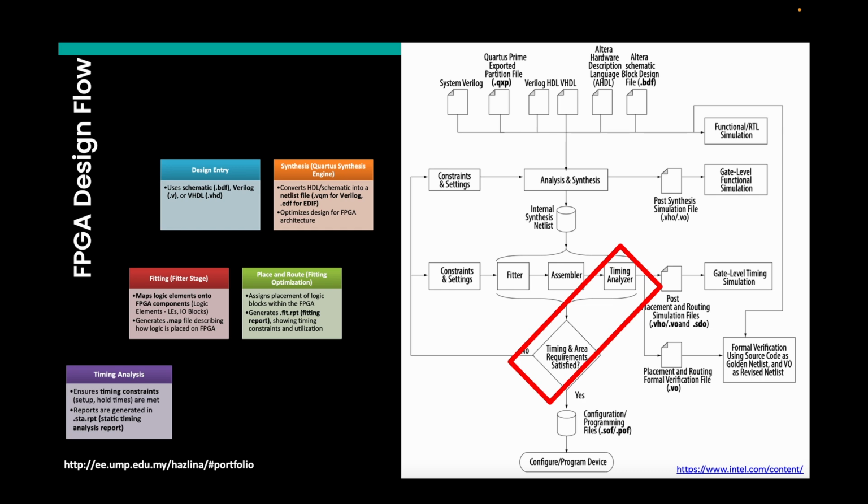Now that the logic is synthesized, we need to map it onto the physical FPGA hardware. This involves assigning FPGA pins for various components. For example, we must carefully allocate I/O pins for the MPU6050 sensors, LoRa transceivers, and LEDs in the DE10-Lite project. This ensures correct physical connections and avoids signal conflicts.